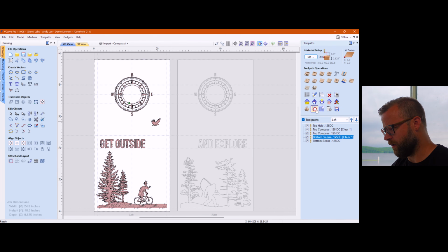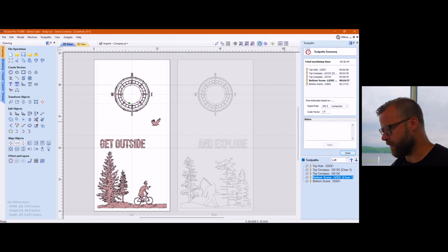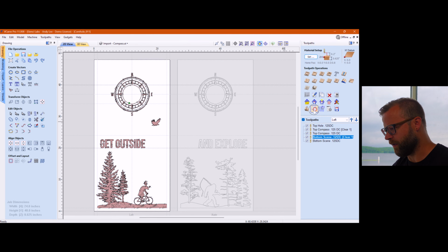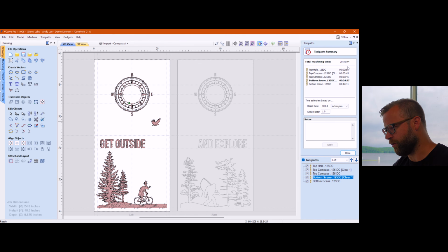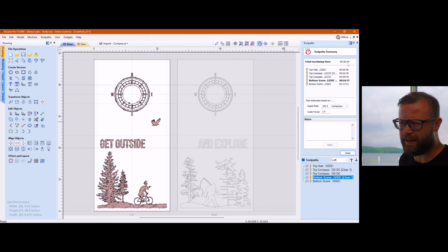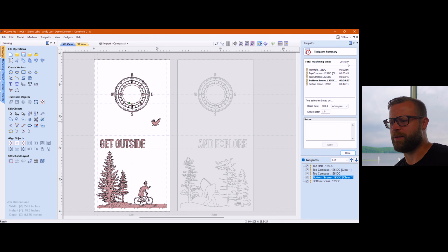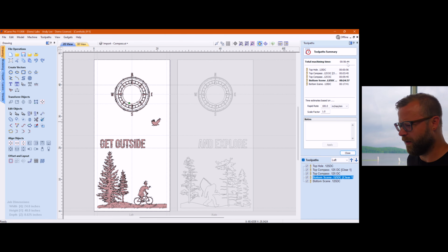Let's select them all and go into here. I guess that's maybe a new one. If you guys aren't familiar with it, it can show you your tool path calculation, your summaries, and it'll show you your time. So yeah, about an hour, but I think I sped everything up in G-Sender, especially the clearing passes, because I was taking off so little material. It was pretty easy to say, hey, let's bump it up. I think I did 120 or 130, but I think that's about it.